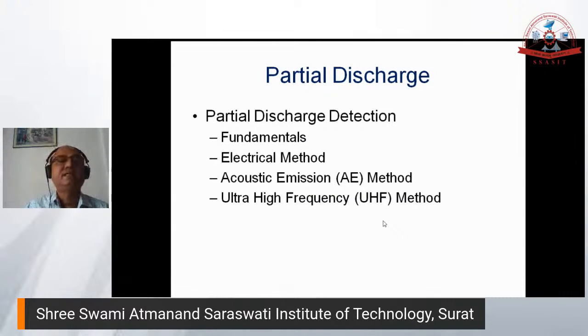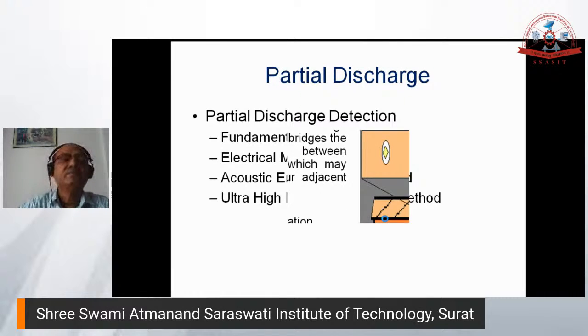Now, partial discharge. In partial discharge, we will talk a little bit about the fundamentals. Those having a high voltage engineering background, or who have at least studied high voltage engineering subjects, will have knowledge of this, so for them some part will be repetition. I will move quickly. We will cover a little bit of the fundamentals because some of you may not be aware of PD. For the sake of completeness, I have given a little about the fundamentals of partial discharge. Then we will talk about the three basic methods of PD measurement: electrical method, acoustic method, and UHF method.